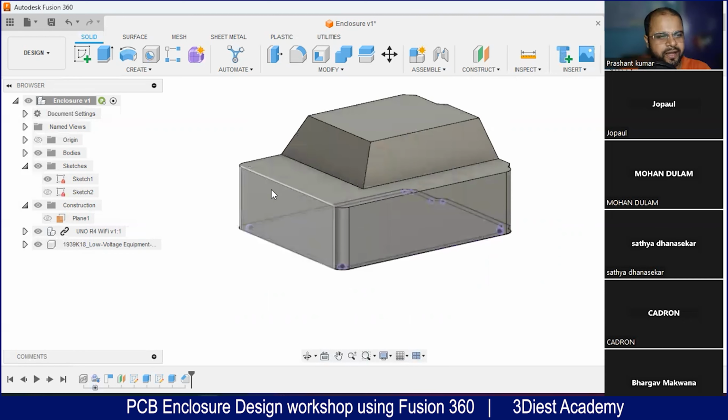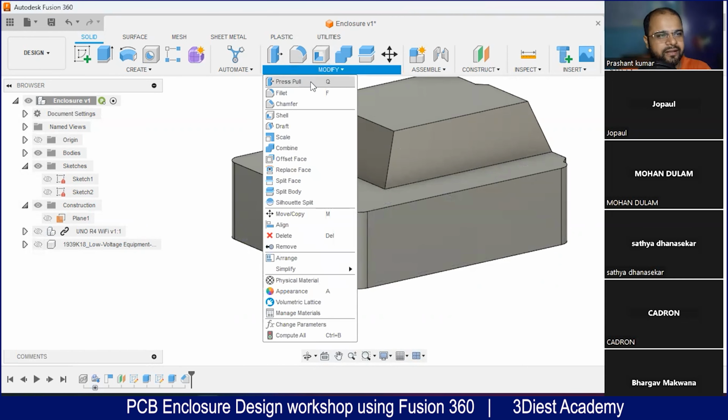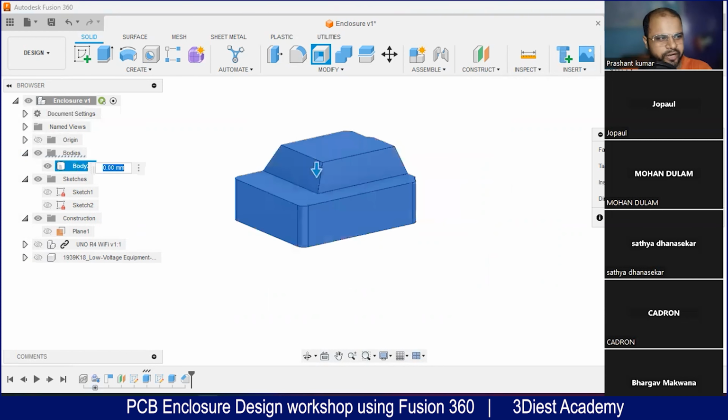Now what I will do, I will turn off the two components, and we'll turn off the sketch also. We'll go on to the modify panel and we'll activate this tool called shell. We'll go on to the bodies and we'll select the body. So here you can see the body just got selected, right? And now I just want to keep an inside thickness of 2.6 millimeters. So I will just give it an inside thickness of 2.6 and we'll press OK.